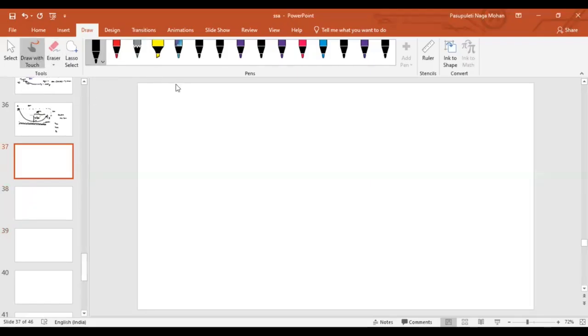Let's start. Let's understand some basics. As you already know this, but still, I just want to explain. Before that, how do we find the deflection or rotation by using the unit load method? If it is an axial load, then we know it is capital P into small p L divided by A E, if it is because of axial loads.